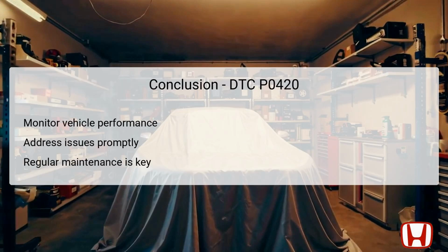In conclusion, managing DTC P0420 requires understanding the catalytic converter's role in the emission system, as well as the components that monitor its efficiency. Maintenance actions, such as using quality fuel, performing routine checks, and addressing any diagnostic trouble codes promptly, can promote vehicle longevity and performance. Troubleshooting steps should be methodically followed, ensuring each aspect is addressed, from clearing DTCs to verifying repairs. A successful resolution not only enhances driving performance, but also ensures compliance with emission regulations.